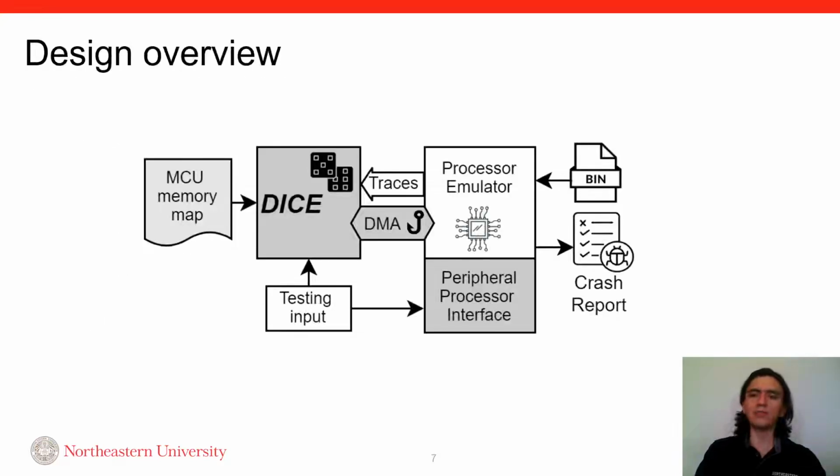The design of DICE adopts a novel approach. Instead of emulating the DMA controller, we design DICE to identify DMA input channels when the firmware configures the DMA transfer into the DMA controller, and then DICE determines when the firmware reads from these input channels and signals the analyzer to provide input data for dynamic analysis.